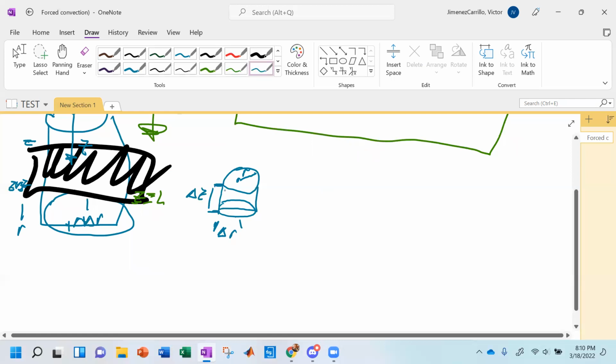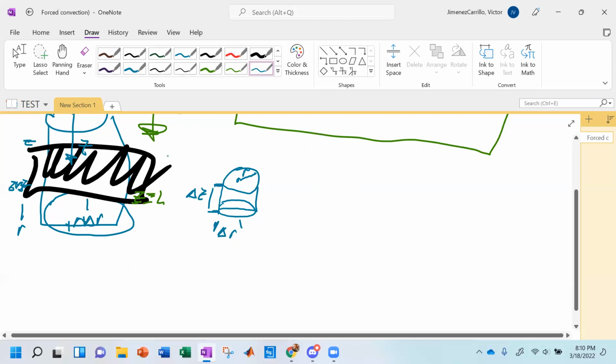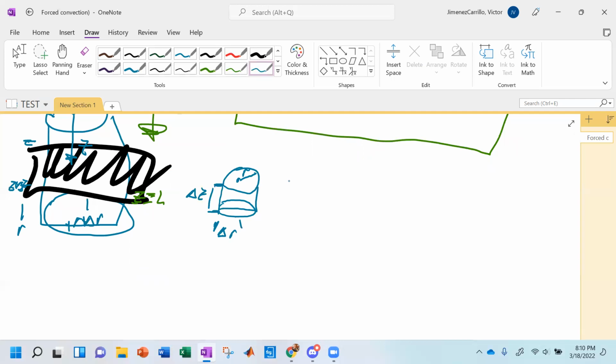Wonderful. Now, we need to talk about energy. The reason this is important is that energy obviously matters here. We're not just talking about heat conduction. There's a velocity component, so we do have taus and we do have 1/2 rho v squared to worry about. But for now, let's take the balance on our shell. The balance we need is the total energy balance at R, at R plus delta R, at Z, and at Z plus delta Z.